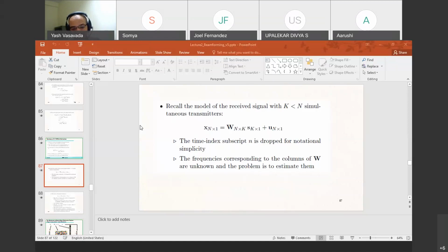And so in that context, we started looking at this FIR filter, the specific type of FIR filter, which is essentially a complex exponential filter. And we saw that if I just take the magnitude squared of the output of a bank of such FIR filters, which actually form the discrete Fourier transform, then effectively I am transforming the incoming signal from the time domain to the frequency domain. And then I'm just essentially getting an estimate of the power spectral density.